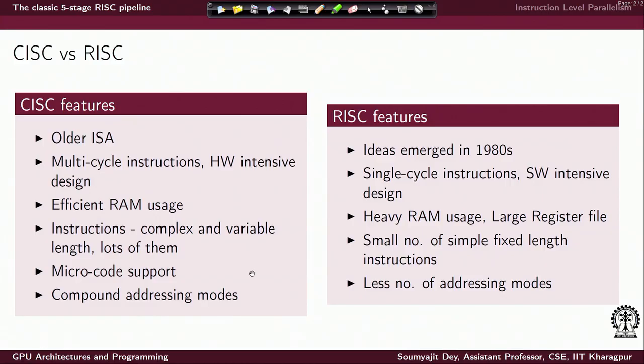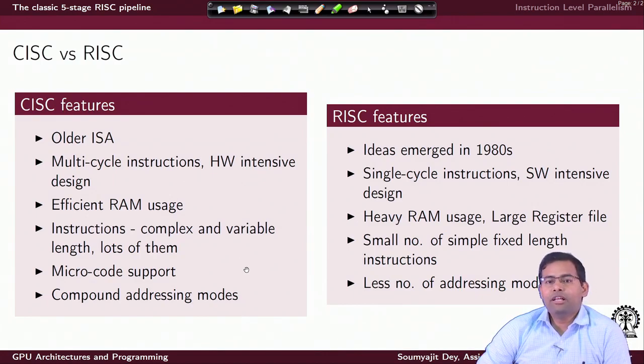In modern days, possibly apart from the x86 architecture, all other processors, more specifically in the embedded world, the processors used in mobile platforms, are mostly following the RISC computing philosophy. In other words, in the x86 world, Intel has still been able to hold on to the CISC philosophy, but internally there is also a question of translation of CISC instructions, but those are advanced topics which we may touch upon later on.